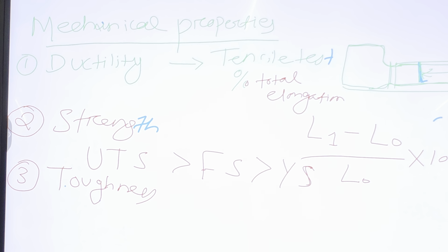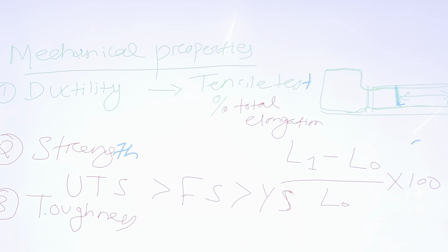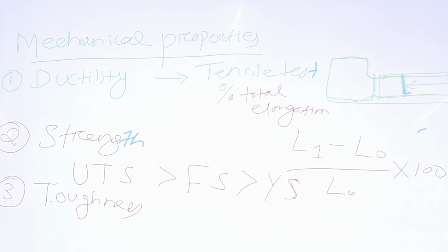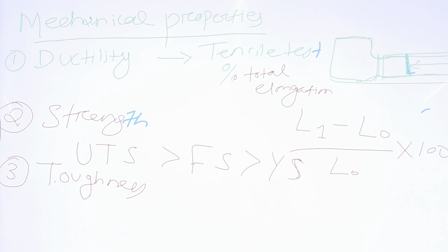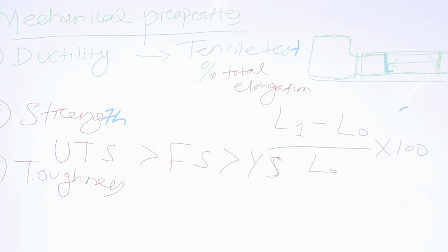Toughness, same, you need to perform a tensile test, you can obtain the toughness. It may not be an exact value, but it will give you some approximate value. What is that? Area under the curve. The area under the curve will give you the toughness. Very good.